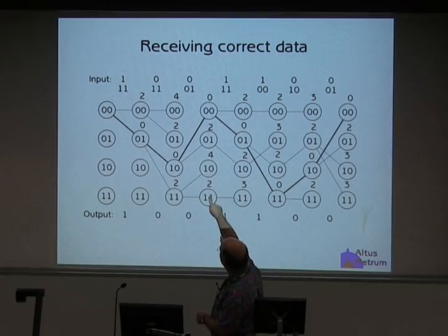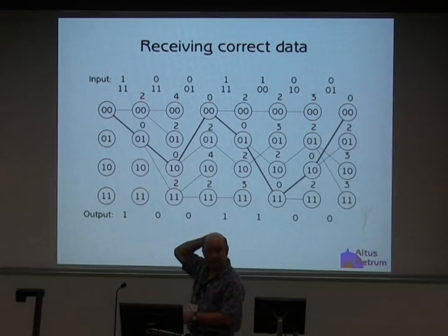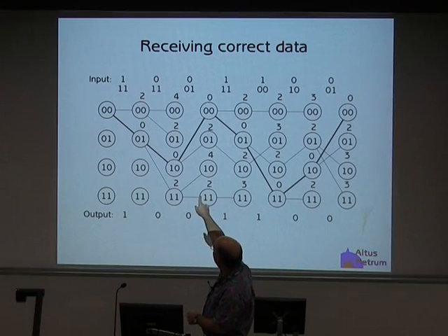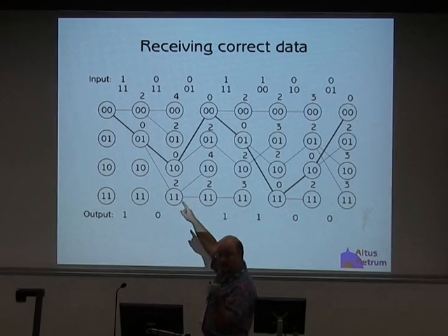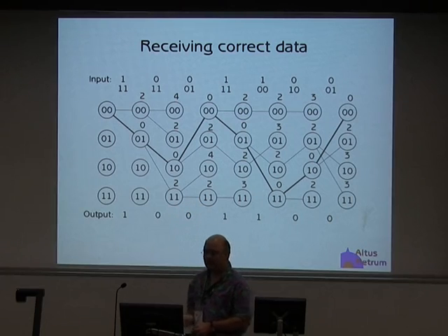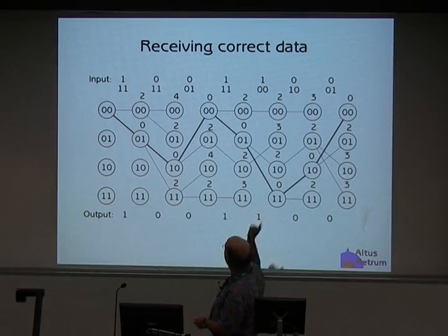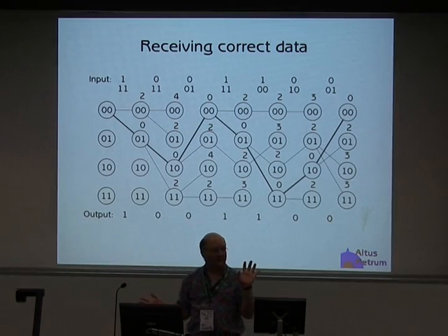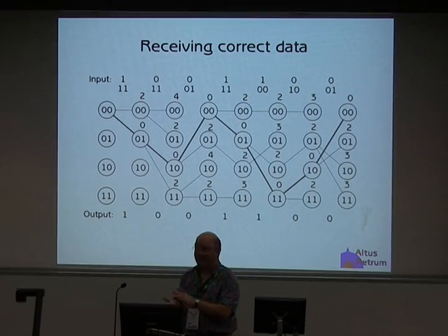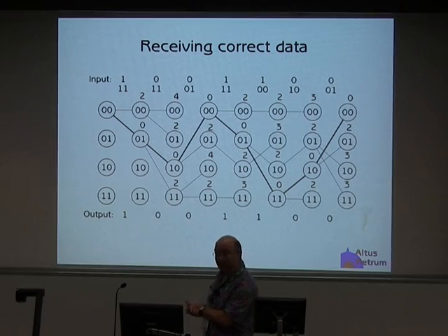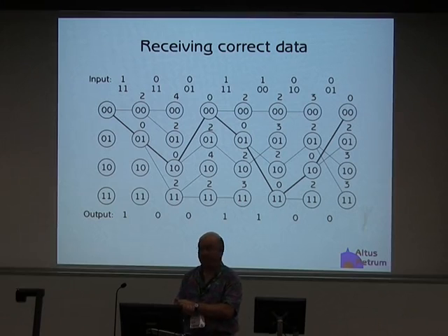And so every time you see a state transition that increases that number, then that state transition had a cost. And again, those state transitions are the difference between the expected value along that path, which I'm not showing here, and you can only see in the original Trellis diagram, and the actual symbol that was received. These slides will be available. This diagram I drew myself. So in this particular one, all the input symbols I received were exactly correct, which is awesome, but it's actually kind of boring, because that meant my receiver was too close to my transmitter and I wasted a bunch of transmit power,